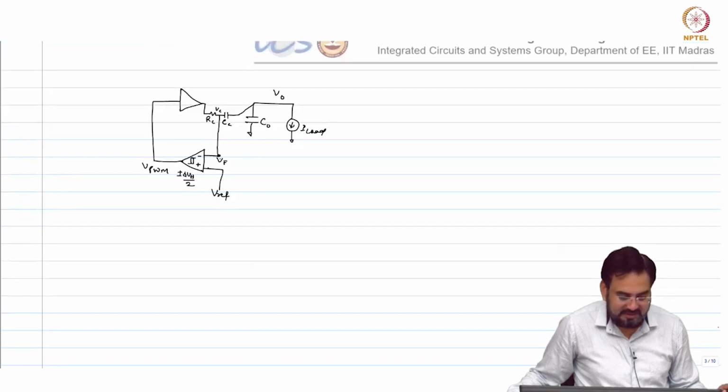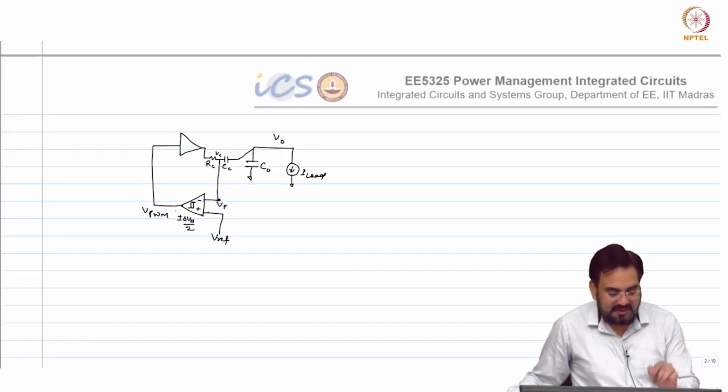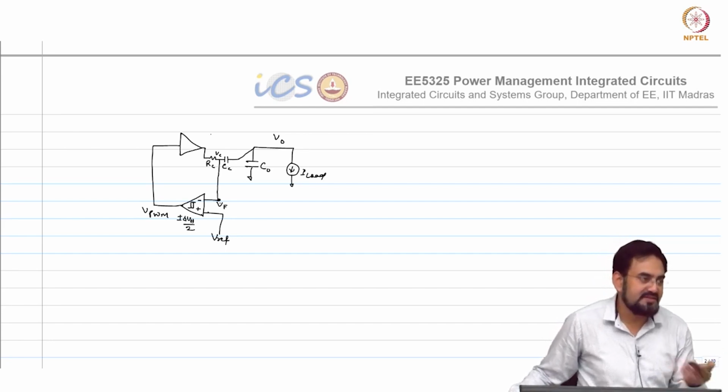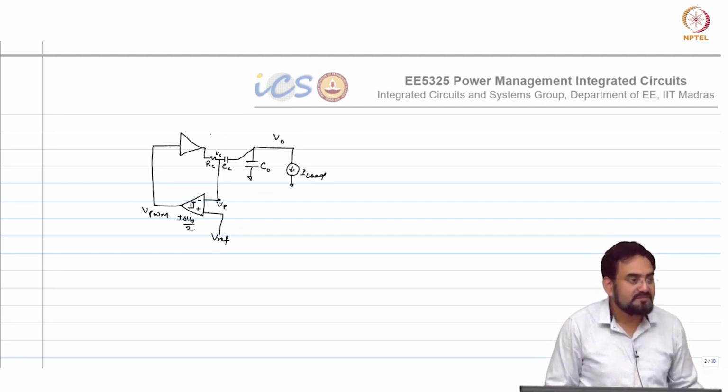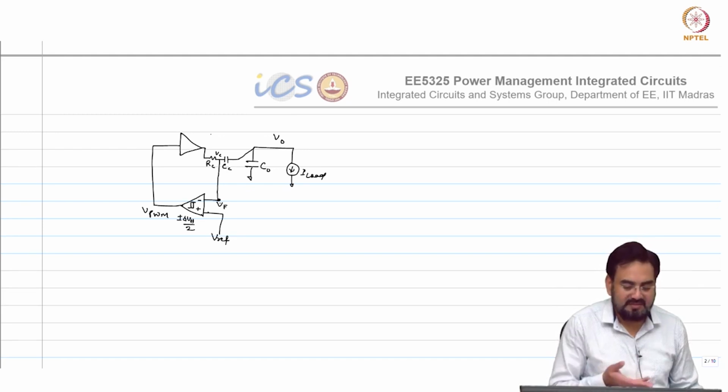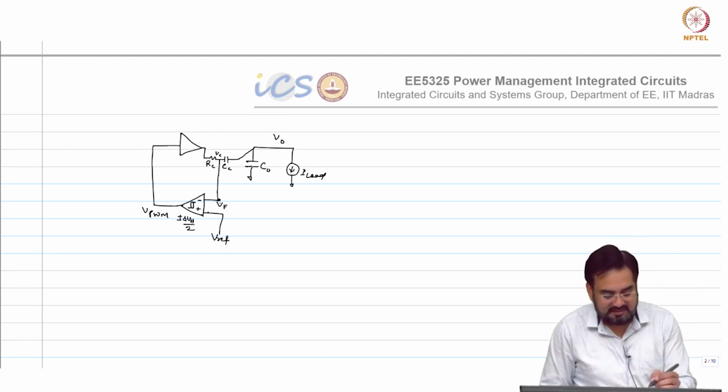and keep only this comparator and RC component, and you can think about this as only a buffer, the gate driver is acting only as a buffer. So, what exactly is this actually? Not a filter, but this is acting like an oscillator.